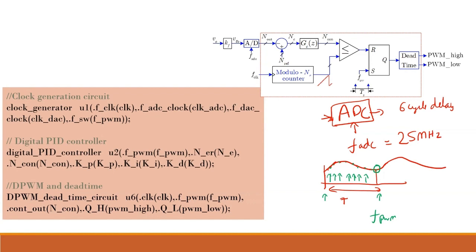If you remember, we talked about how we cannot define a module inside a module, but we can call or instantiate a module. So there's a DPWM underscore VMC. This is our main module. In that module, we are calling this module, the dead time module, etc. All these modules we are calling inside this module. And these are the arguments which we pass on to it, using this dot notation, which we had explained last week.